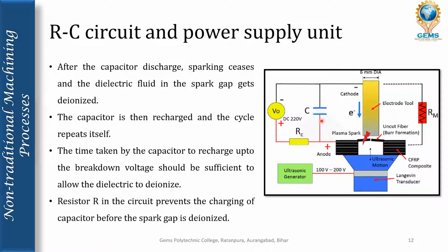Here, the time taken by the capacitor to recharge again up to the breakdown voltage should be sufficient to allow the dielectric to deionize. It means the time the capacitor takes to recharge is enough for the dielectric to get deionized.